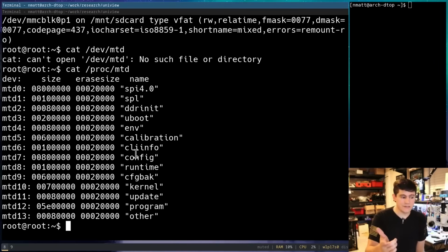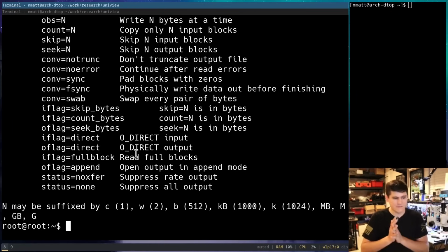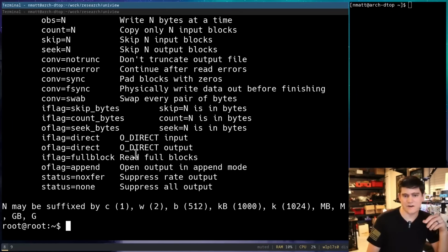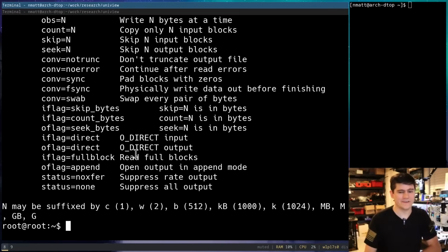Okay, so here we can see all of the flash partitions that are on this device, and we can use the dd command, which it does have on here. It gives us a bunch of useful commands that will allow us to dump the firmware without ever desoldering the chip off the device, which is nice in certain circumstances. And if we're developing an exploit, if we have reverse engineered the binaries and we think there's a vulnerable network service, it's so helpful to be able to potentially get your debugger to run on the target device.